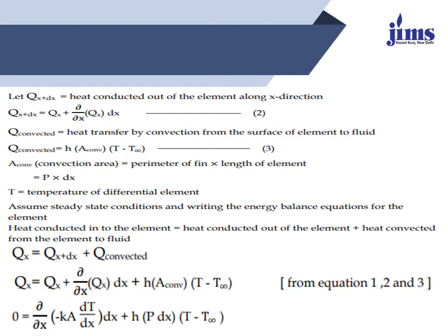Putting the values of equations number 1, 2 and 3, we obtain 0 is equal to del over del x of minus KA dT by dx, plus hP dx into T minus T infinity. This is the mathematical expression for the heat transfer through a rectangular fin.